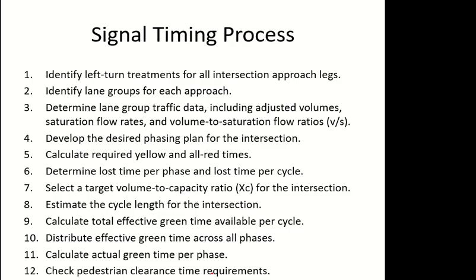In most cases it goes like this, because in a city, if some signals have permitted left turnings and some signals have protected, it will be very confusing for the drivers. So the practical solution, on signals where you want to make them permitted, to avoid confusion, is we just keep it with the straight. Obviously when the straight goes, drivers may find the left turning allowed as well.